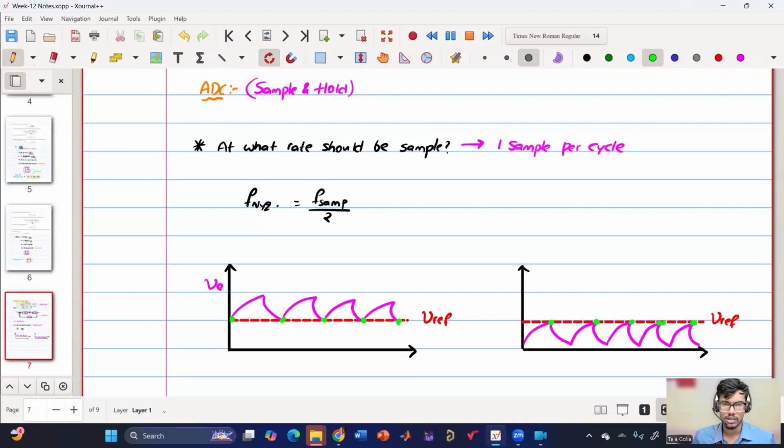So there are multiple ways of doing. In the case of average current mode control, you are taking average, something like that. Here also you can take a sample in between the on-time or off-time. Again, there can be a question: how do we know on-time? How do we know off-time? So you can take at the middle of the switching frequency. But in the case of constant on time or constant off time, one of the values is known, so you can take at the middle point.